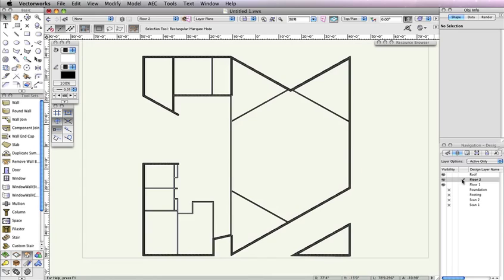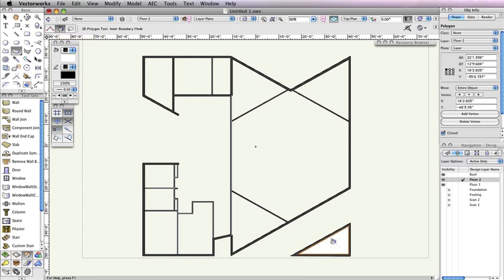Let's start with the flashing for this triangular roof first. In the Basic Tool palette, select the Polygon tool. Also, choose Inner Boundary Mode and click on the space inside of the triangular roof. As soon as you click in this area, a polygon should be created that fills the area. This will be the path for this particular roof's flashing.